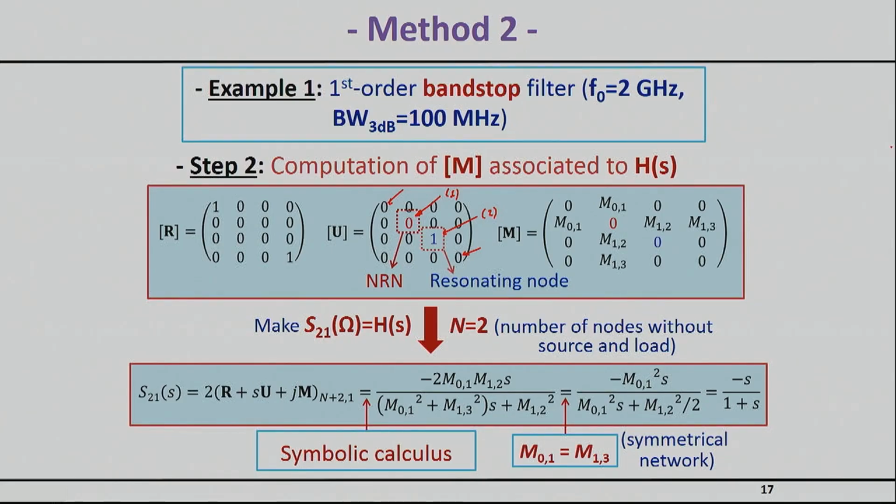Now, for the coupling matrix M, normally we would have a choice for these 2 numbers. If, for example, we had a non-synchronous filter, this one might have been different than 0. Here we'll assume we have a synchronous filter, so this one will actually be equal to 0. This one represents, though, the non-resonating node, and that means we're going to set this equal to 0. So these are essentially the 2 main changes we're making into the coupling matrix framework once we are dealing with non-resonating nodes.